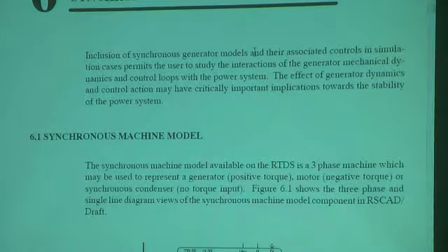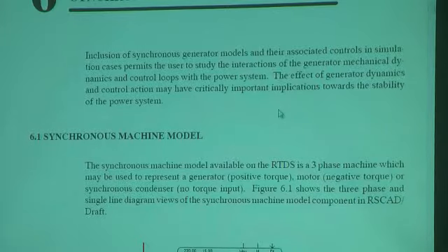And using these models allows you to look at the effect of the generator dynamics within your control loop. And it could uncover stability issues with the power system, you know, as long as your network and controls are modeled accurately.